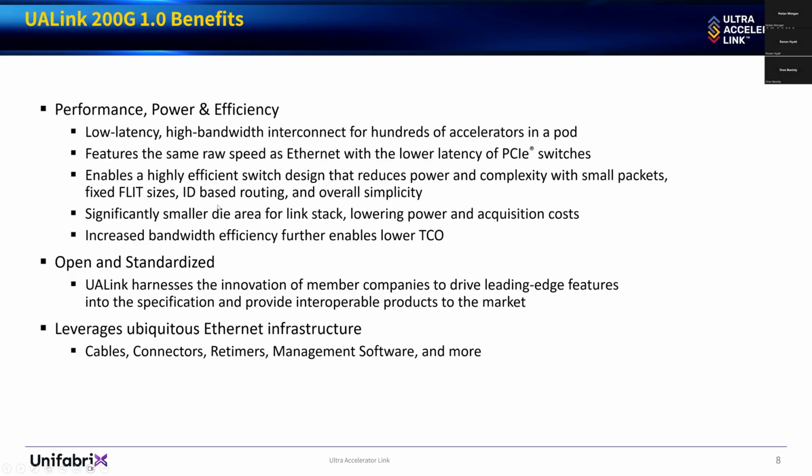ID-based routing, meaning each of the accelerators, each of the entities that participate in a UALink fabric has its own ID. And switches and accelerators, when they have to decide how to route a message, a packet from one place to another, use this ID to bring the packet to its place. The word simplicity repeats multiple times. This is one of the design goals of UALink. It helps a lot in creating multi-vendor interoperability. Everything is simple, everything is well-defined.